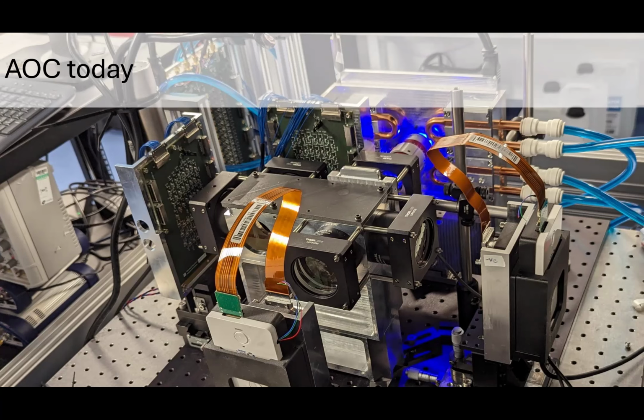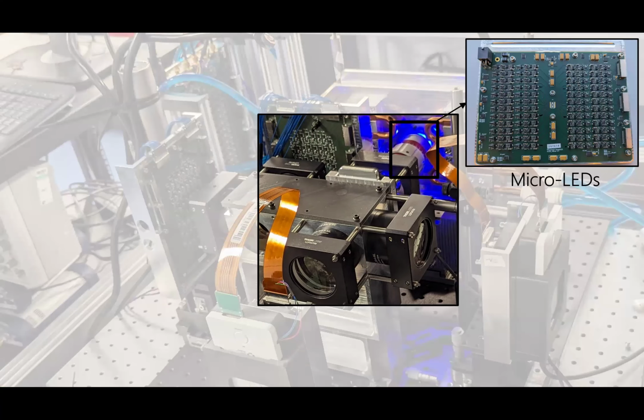But at this stage, let's go through the diagram. So zooming in on the interesting bit in the middle, you can see that blue glow there. That's some light coming from an array of micro LEDs. So our optical sources in this setup are micro LEDs. The chip that controls these micro LEDs is about the size of an A4 piece of paper, and that's what you can see there in green. And the LEDs themselves are that little tiny bit in the middle under the laser pointer, and all of the rest of the stuff is discrete PCB level amplifiers and drivers. And that's something which would need to be shrunk down again when we scale up.